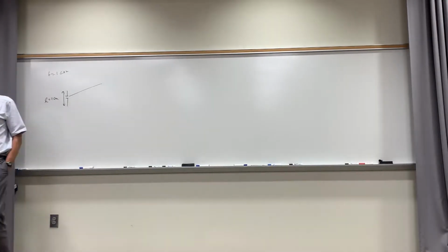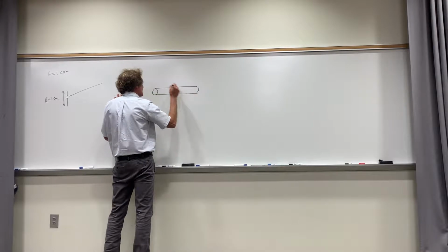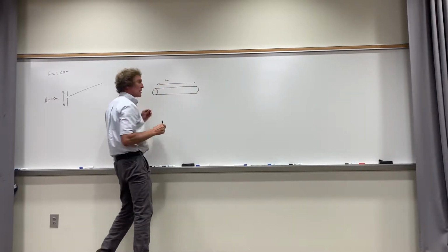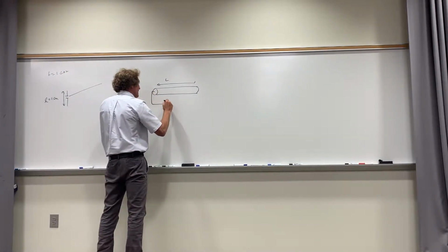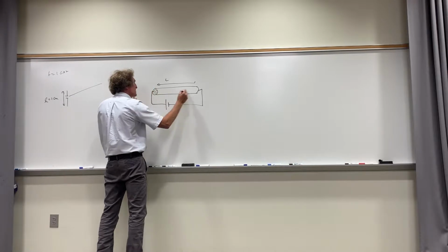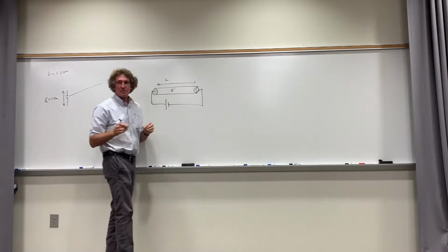Okay, we didn't talk about gain, that was the topic for today, but let me just show you something. Whenever you deal with any real wires, they have a finite resistance. And you remember back in EMAG 1, you learned about skin depth. You all remember that? All right, so the way you look at this wire, you look at it as just a long tube or cylinder of length L. Now, if you think about the resistance of a long tube, you're going to put a conducting surface at each end. This has some sigma. That's sigma of copper, right?